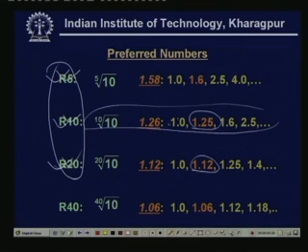That means you can have 1000, 1215, 1600, 2500 like that. What I am doing is multiplying by a multiplication factor. You can have the powers of a tractor engine maybe 10, 16, 25, 40, something like this.